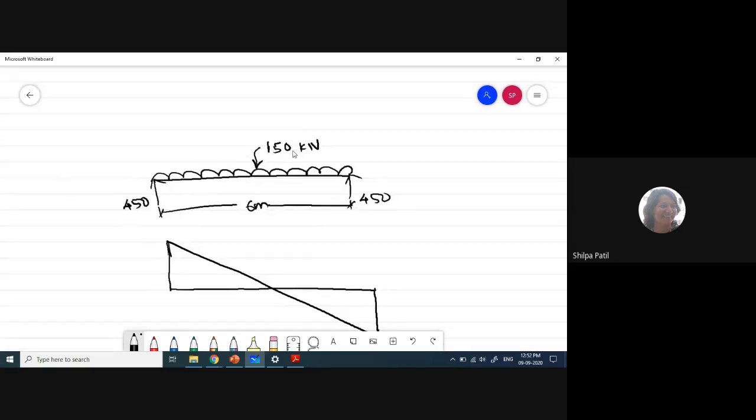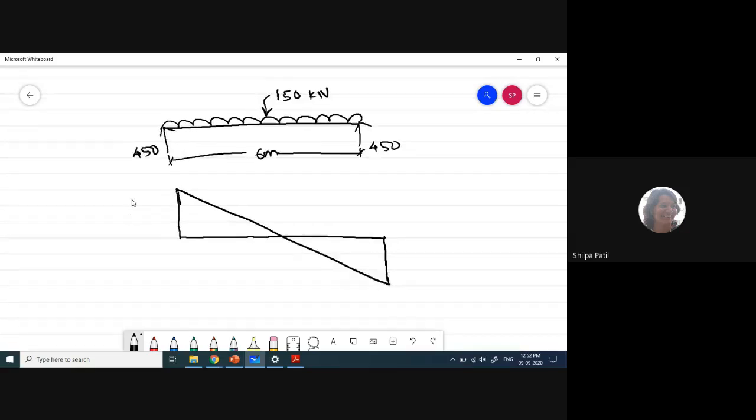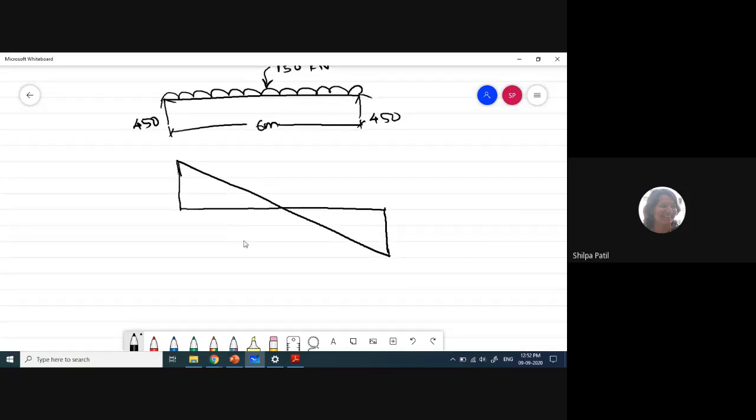Okay, now in this entire diagram, we have to consider the zones. Now, as it is mentioned in the problem statement that two bars are bent up. Now, the bar bent ups are normally done at a distance of L by 7 from support. Just write down one statement: bars are bent up at a distance of L by 7 from support. So from this support, if this is my L by 7, at this distance the bar will be bent. Okay, so obviously we have to consider the zoning accordingly now.